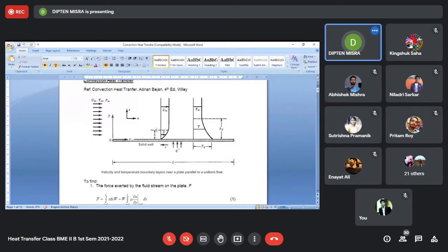Now this thickness of the boundary layer is not constant. What we will see is that this thickness of the boundary layer will increase with x in a particular manner, so the boundary layer zone is not a zone of uniform width or thickness. Rather, it is a zone whose thickness increases gradually from 0 at this point, which is called the leading edge of this flat plate. At the leading edge, the thickness of the boundary layer is 0, and then it grows gradually.